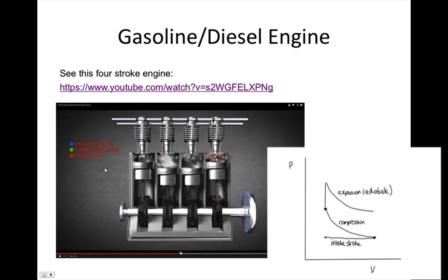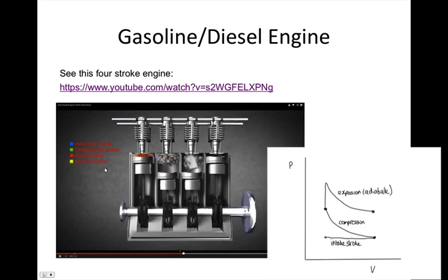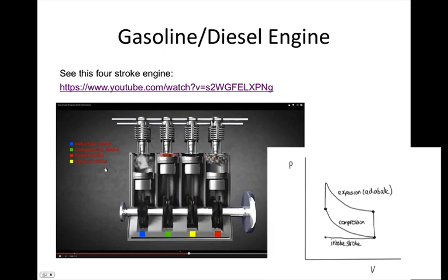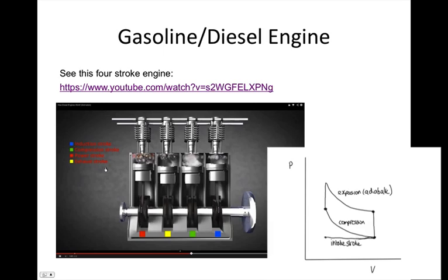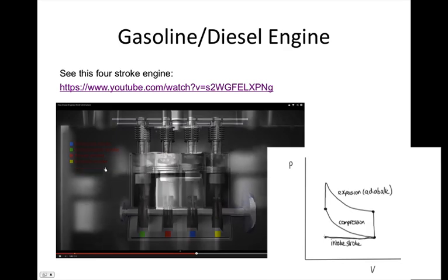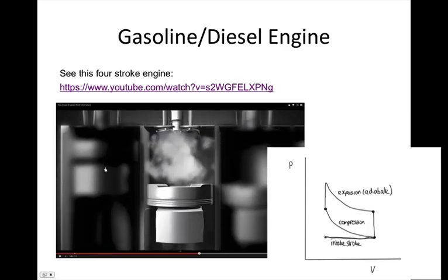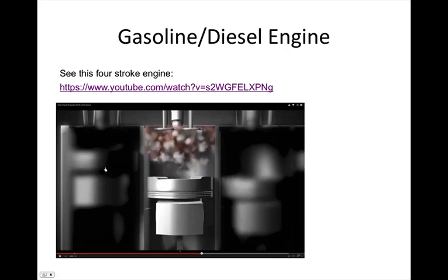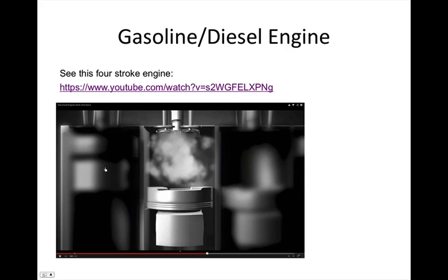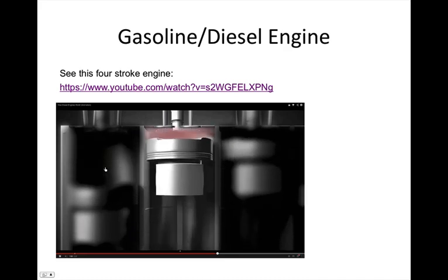At that point, the exhaust valves open, and so the pressure drops to the external pressure, and the cylinder is then compressed again in order to get rid of all the excess gas inside the cylinder. The engine has 4 strokes to ensure that one of those pistons is always undergoing the expansion, i.e. one of them can always provide the work to keep the shaft turning.